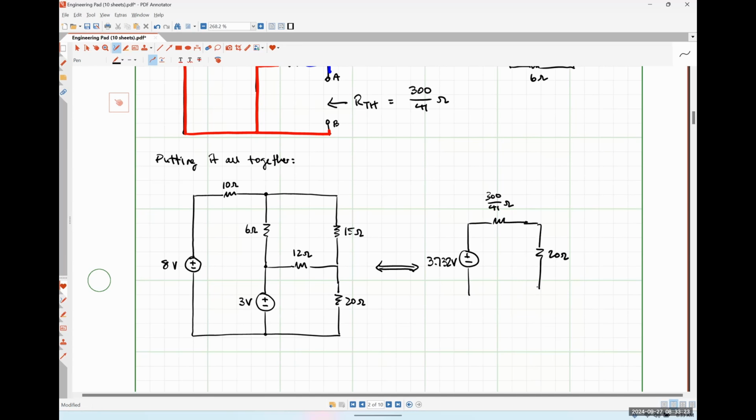And then this is our 20 ohm resistor. So we can replace all of that big ugly network that was connected to the 20 ohm resistor by literally a practical voltage source using this method. For what it's worth, the source transformation thing that we learned in our last class meeting is effectively pointless now. Because instead of flip-flopping back and forth between different forms, we can start with a practical voltage source connected to an arbitrary load resistance and find the Thevenin equivalent with respect to the load resistance, and we wind up with the exact same result, but we have a lot more freedom in how we get to that end result, right?